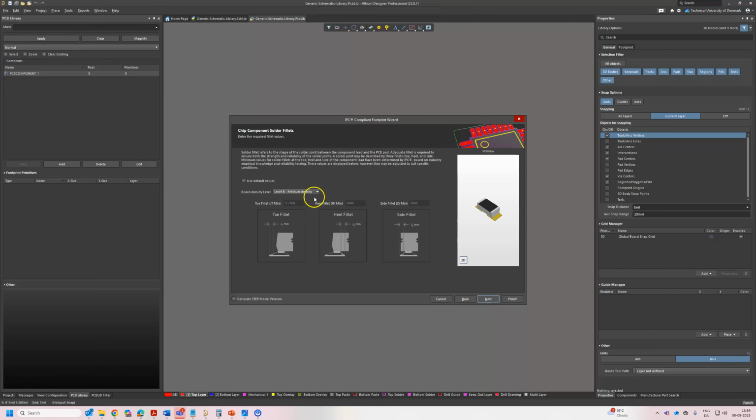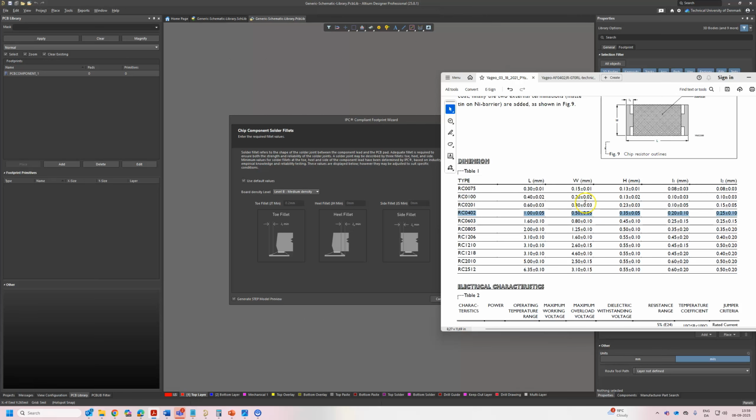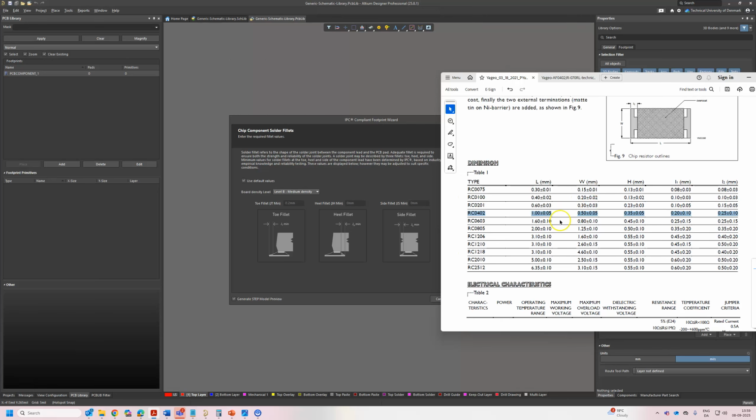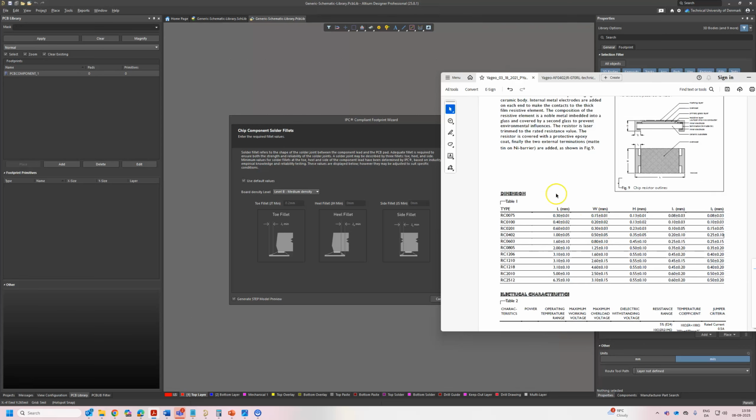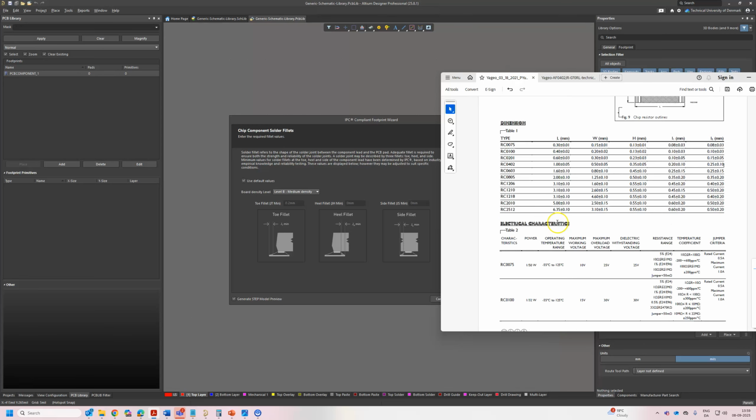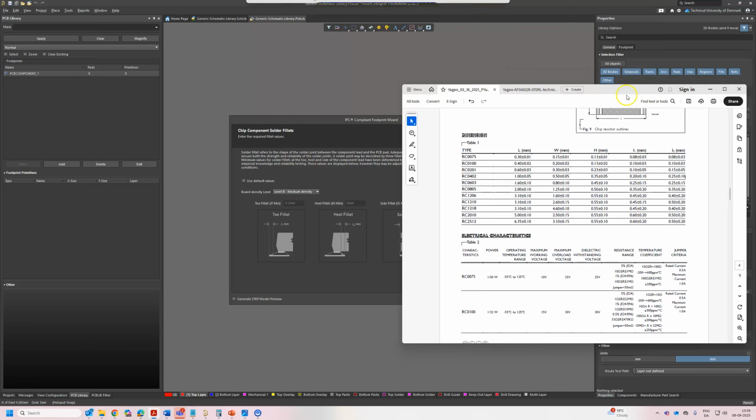The density level, I keep it level B. If you want really low density, you can put it level A. Then there will not be a lot of spacing to solder your components, especially if you do it by hand. And if you notice in the data sheet, this is for reflow. This is for reflow oven, but it still works with hand soldering.